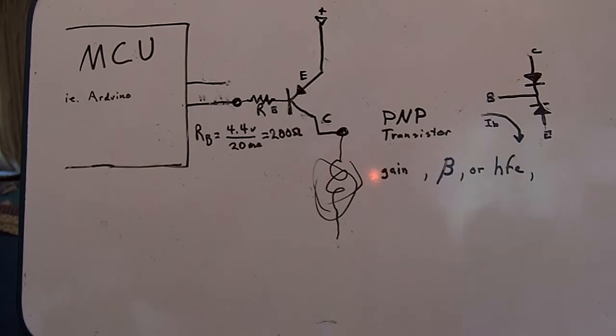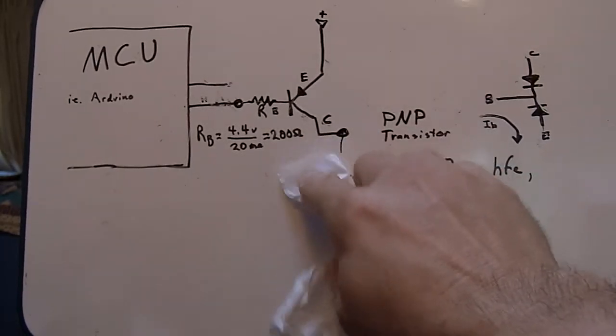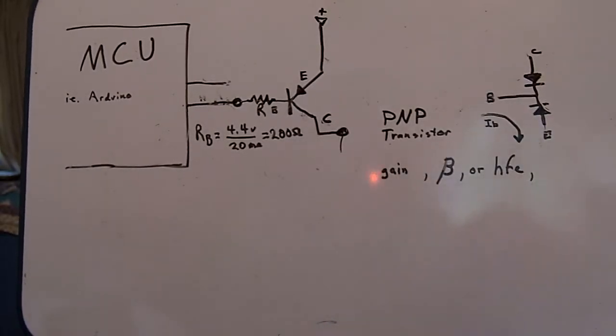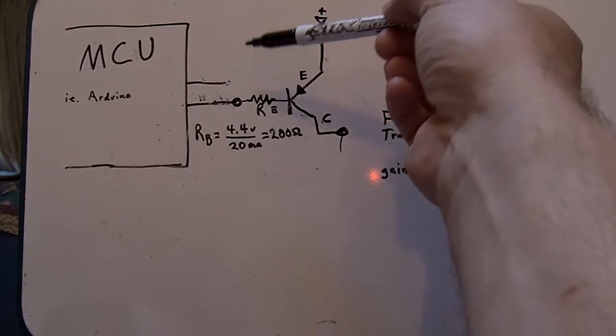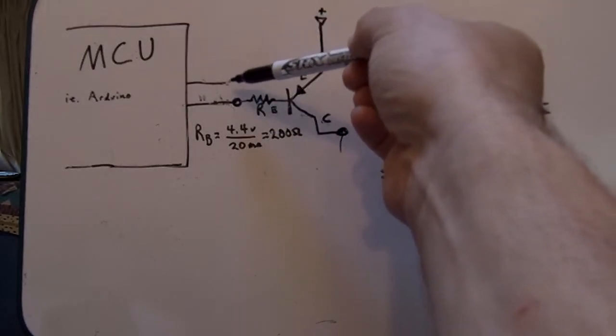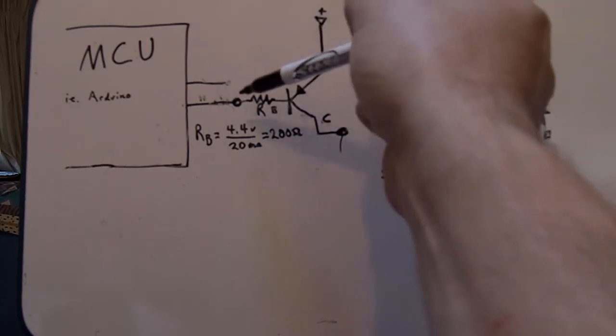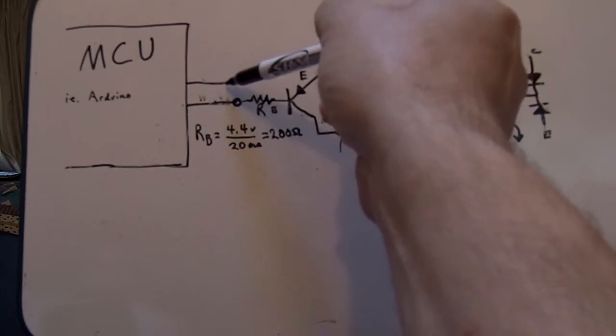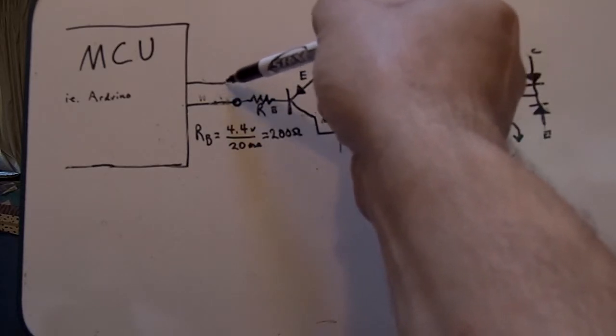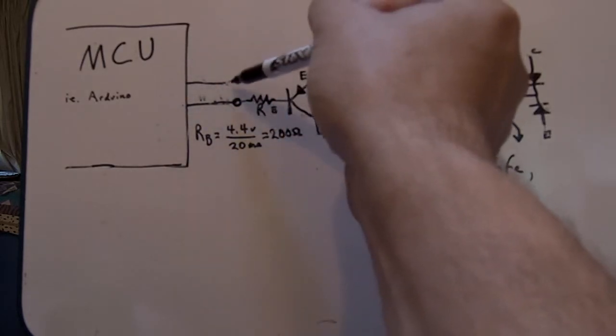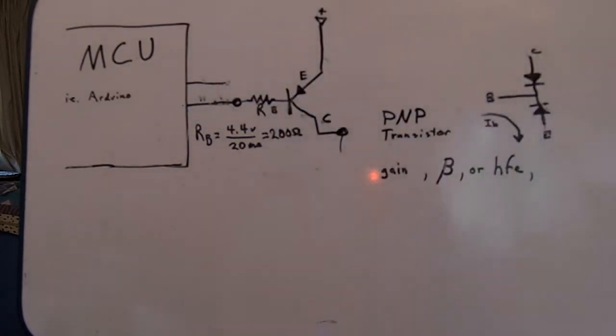The other thing I could do, of course, would be to run a relay. Now, a small enough relay, they make very small relays called reed relays or dip relays, and a lot of them are about the size of a dip container, and they have very low current capacity in the coils. And you can actually run the coils directly from an MCU. You may not even need snubber diodes because they're pretty much built into the MCU for something really tiny like that.